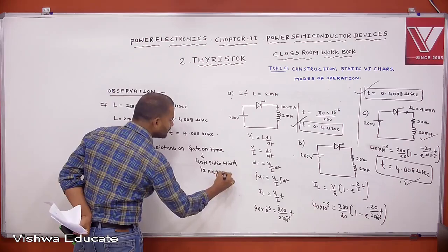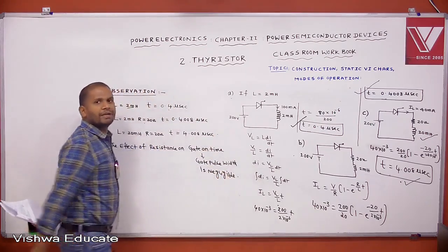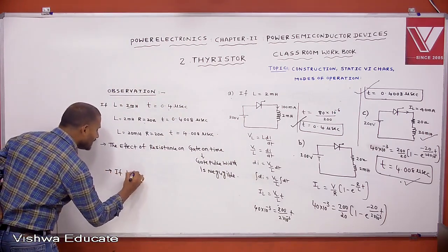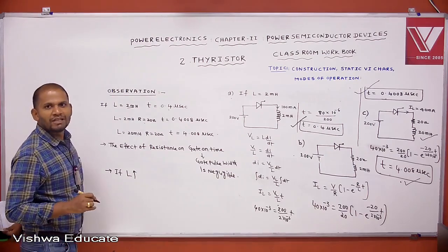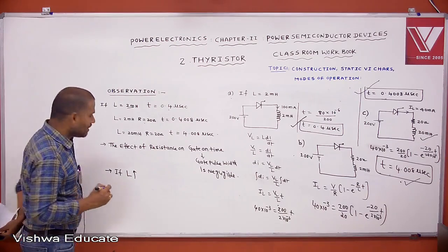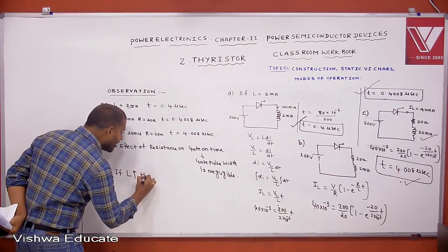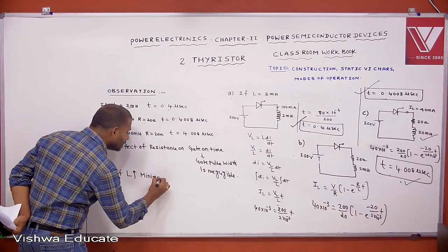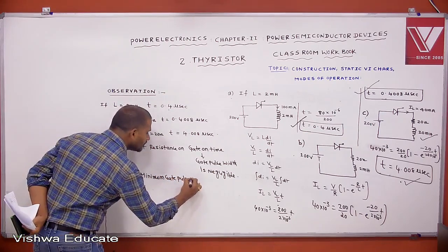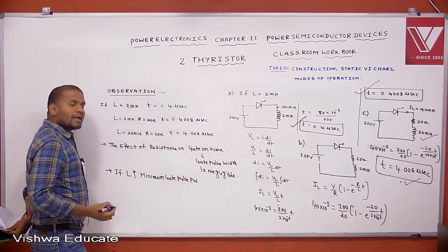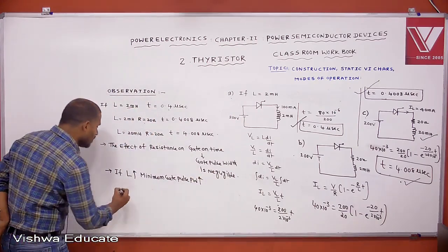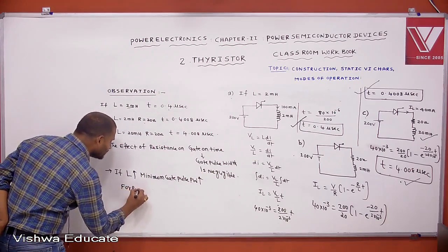It is independent of the resistance. Second observation: if the load inductance increases, then the minimum gate pulse width also increases for reliable turn on of the SCR.